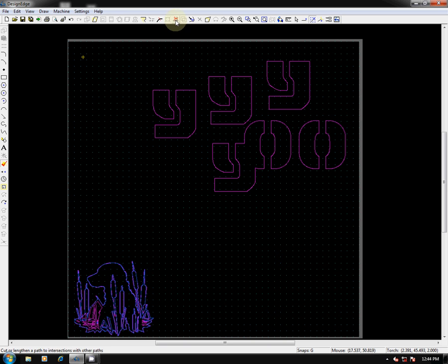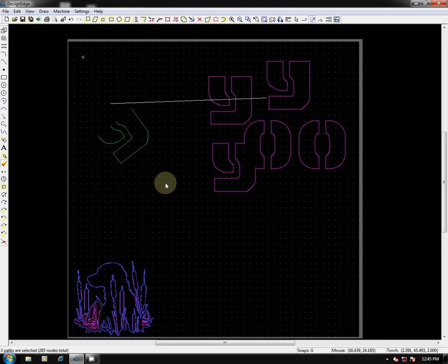There's also cut. So say we had a line, which over here on the left, going through a part for whatever reason, and we wanted to trim some stuff off, we can come up to these scissors and trim off what we don't want, if we wanted to. We could rotate our parts. So you can highlight what you want. We can come up here to rotate, which is kind of like a skew square. We're going to select a pivot point and then select where we want it on what we've selected to move from. We can pivot it. You can do like a double click pivot to where it's like a real tight and it'll rotate right in position.